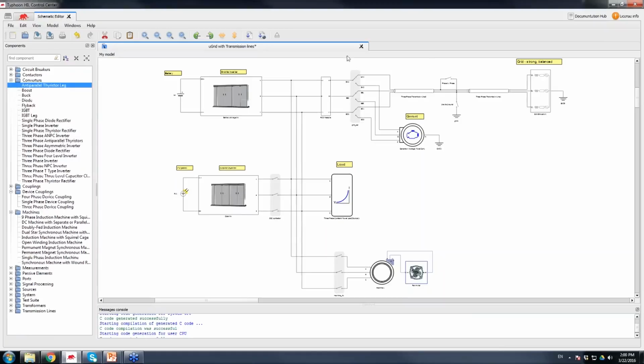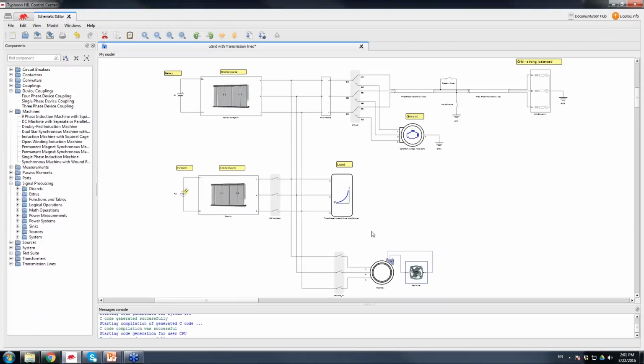So this is the part of modeling the power stage, something that we are going to run with extremely low time steps in order of 1 microsecond or sometimes even faster. This example that you can see right here, all of this we are going to simulate with 1 microsecond update rate. Again, to further customize these kind of models, there is also additional layer of modeling available.